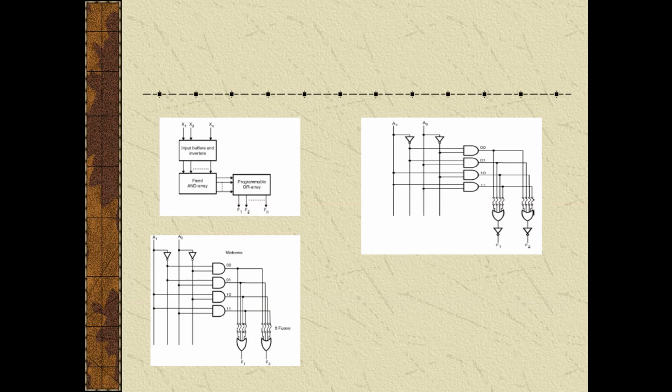Let's see a few advantages of ROM and PLDs. As no minimization of the logic circuits is needed, the circuits can be designed easily, and it is possible to modify the circuit faster. These are high speed as compared to discrete circuits, and cost is also lower. These are all about the PROM. In the next slide, we will see about the PLA.